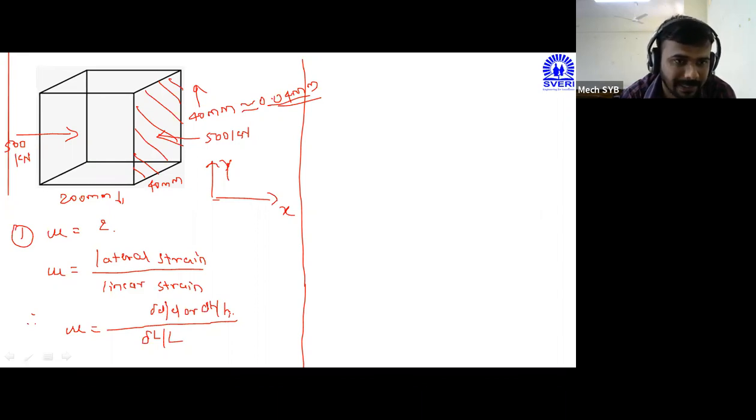लिनियर स्ट्रेन म्हणजे तुम्हाला फिगर मध्ये दिसतंय की X डायरेक्शन मध्ये फोर्स अप्लाय केलेला आहे, त्यामुळं X डायरेक्शन मधला स्ट्रेन हा लिनियर असणार आहे. पण X डायरेक्शन मध्ये कुठला पॅरामीटर आहे? लेंथ. म्हणजे चेंज इन लेंथ अपॉन ओरिजिनल लेंथ म्हणजे लिनियर स्ट्रेन झाला. बट थिकनेस इज प्रेझेंट इन Y डायरेक्शन. थिकनेसचं डायमेन्शन फिगर मध्ये व्हर्टिकल मध्ये दिलेलं आहे, पण त्या व्हर्टिकल डायरेक्शन मध्ये फोर्स अप्लाय झालेला नाही. फोर्स हा फक्त हॉरिझॉन्टल डायरेक्शन मध्येच आहे, पण थिकनेस पण चेंज झालेला आहे, म्हणजे इन्क्रीज झालेला आहे, म्हणजे त्या डायरेक्शन मधला स्ट्रेन लॅटरल स्ट्रेन. सो नाउ पुट द व्हॅल्यूज.